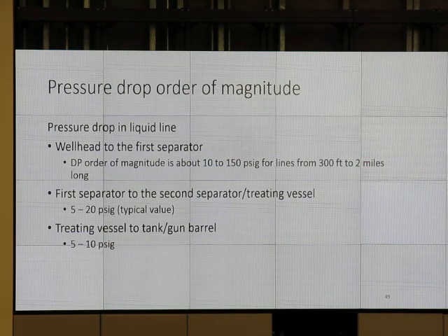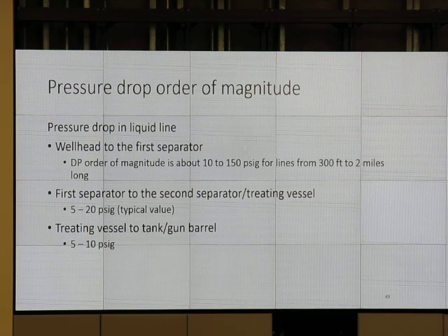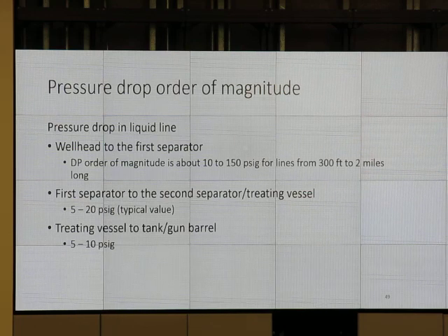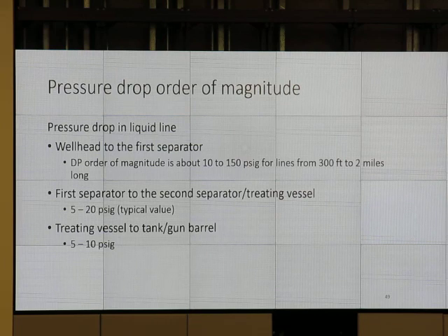If I'm supplying pressure to push something to an atmospheric tank, I don't need as much pressure drop. I'm going to get some hydrostatic head help from whatever vessel I'm coming out of, but my operating pressure's got to be high enough to take that hydrostatic and a little oomph to get it to the top of the tank. We nearly always fill our tanks from the top of the tank. So you're going to always have that pressure of that full height of your tank to contend with.